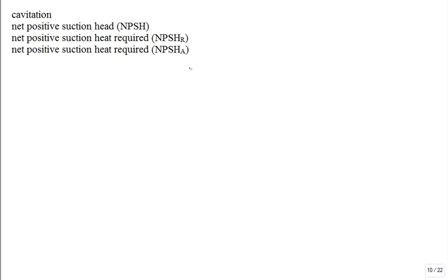It's very damaging to pumps, internally to pumps. And it's caused by saturation. It's caused by vapors forming or gases forming in your liquid, and then little bubbles will form. They like to form in low pressure regions. And then when the fluid is swept with the bubbles to a high pressure region, what does the bubble like to do? Goes away. And it goes away and it creates a little ping, pop. And then that's a pressure pulse. And on surfaces, it's like that high-low pressure that actually pops off metal to cause the erosion. So anyway, cavitation is a major problem in pumps.